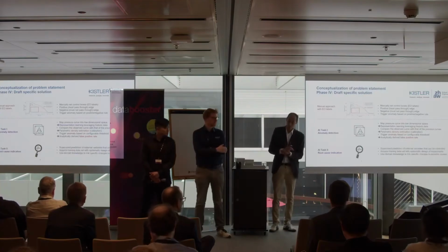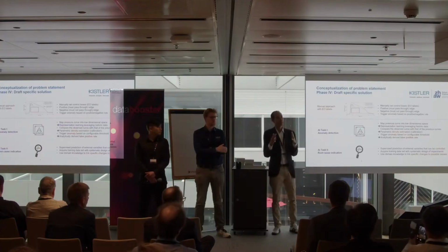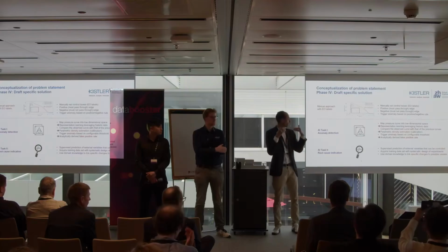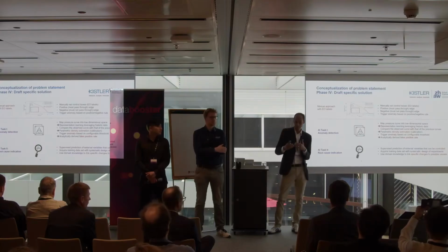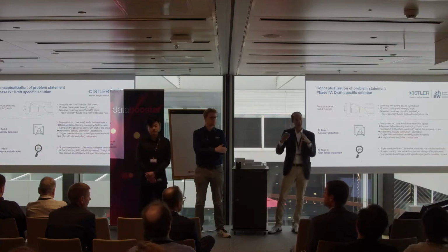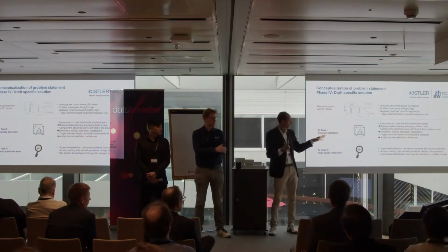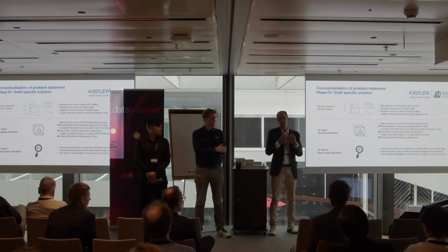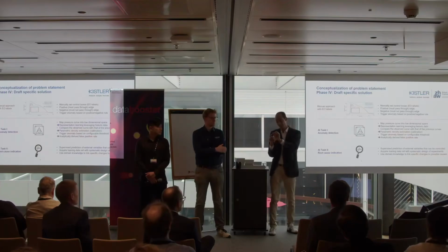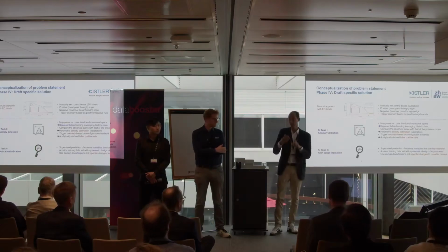So for the root cause identification, this is a bit more complicated. Here, the basic idea is to acquire data from or link data to external variables that we can control, and then learn systematic effects of these variables. The variables that we chose are three machine parameters that can be set at the machine: the back pressure, the injection speed, and the mold temperature.